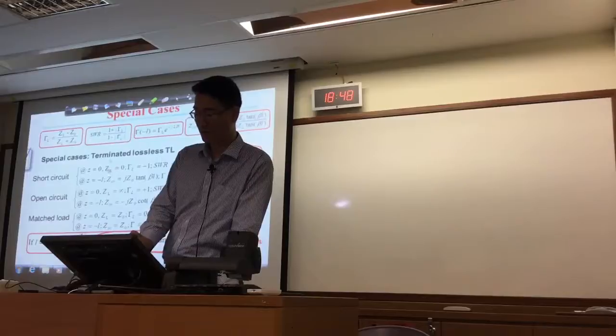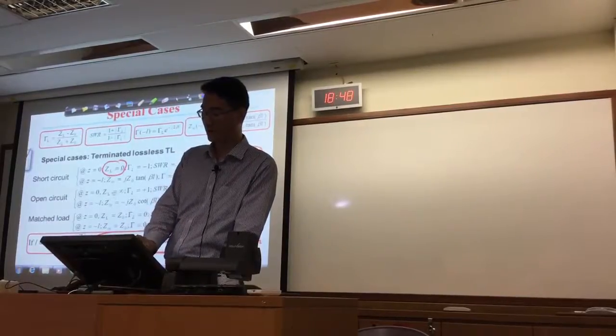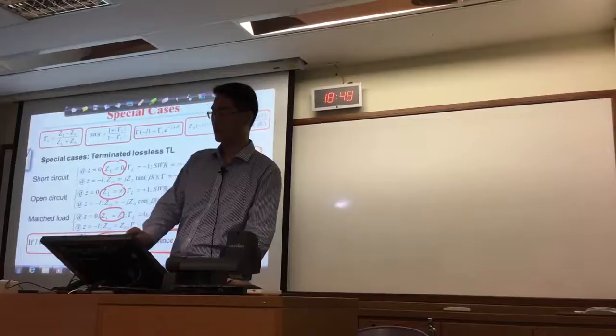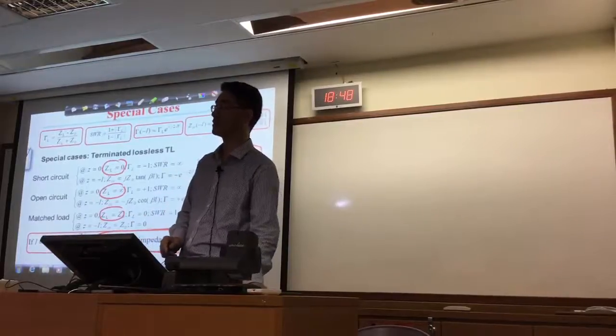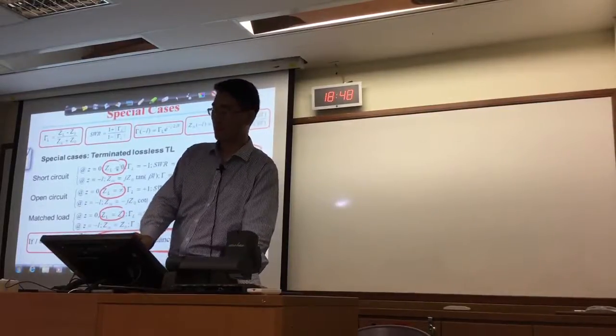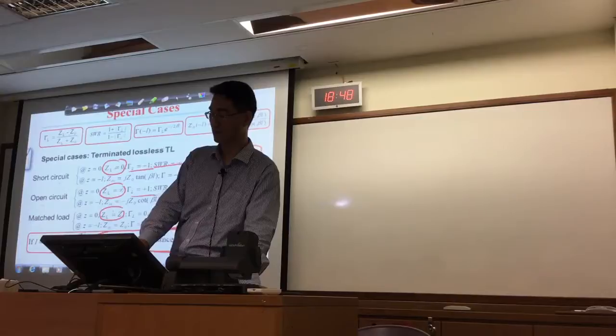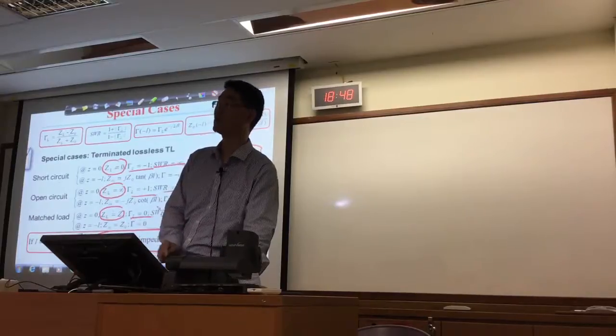For short circuit, the load impedance is 0. For open circuit, the load is infinity. Match load means the load impedance is equal to the characteristic impedance. Then substitute all this into this equation, then you get the SWR and reflection coefficient, right?